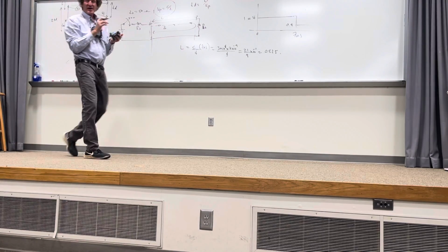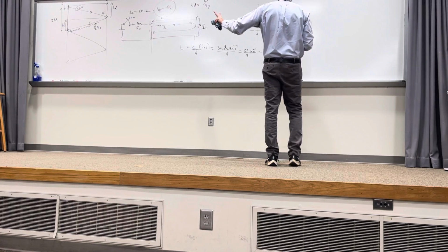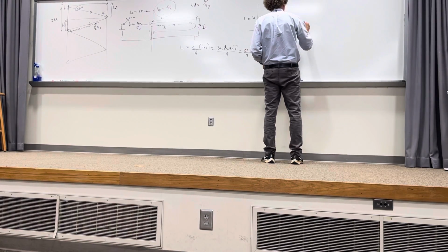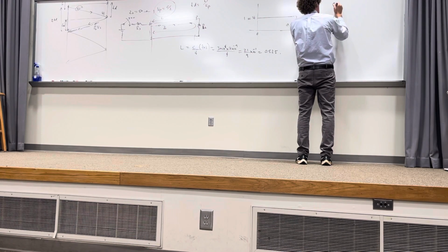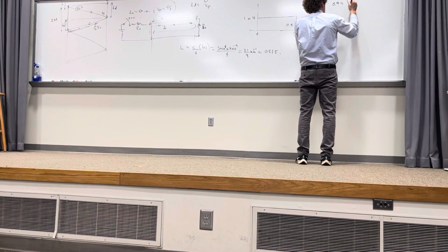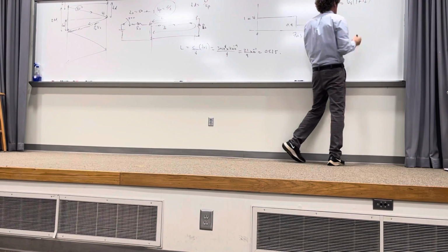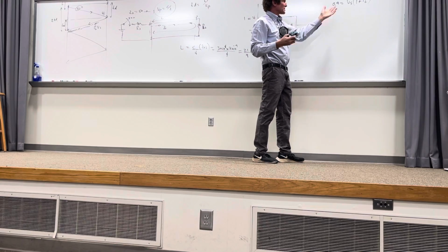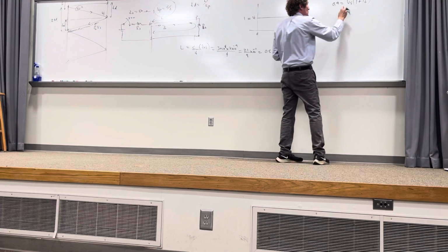Y'all follow me? By the way, that is the transmission coefficient at that point, but I'll get to that in a second. So VS is 1, so I know 0.4 would be equal to VS times 1 plus the reflection coefficient at the load. I know VS is 1, correct, class? Yes. From the diagram, so I just leave it as 1.